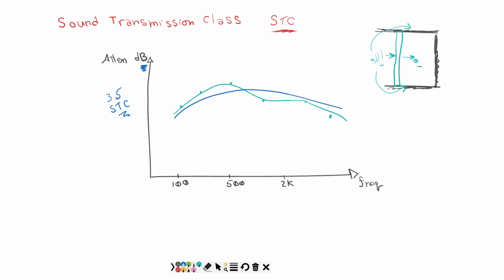When you get up to maybe 45, it's just going to be sort of a dull roar that you're going to hear. Yeah, there's something going on the other side of the wall. I can't quite tell what it is. When you get up to maybe 60, 70, well, now you're approaching an area that some people would mistakenly call soundproof, right? Like I said, there is no such thing as soundproof. But the loss is so great that you may not even be able to tell that people are yelling over here, right? I got people over here yelling, and on this side, you can't hear it, right? Because you got an STC of 65 on this barrier, all right?